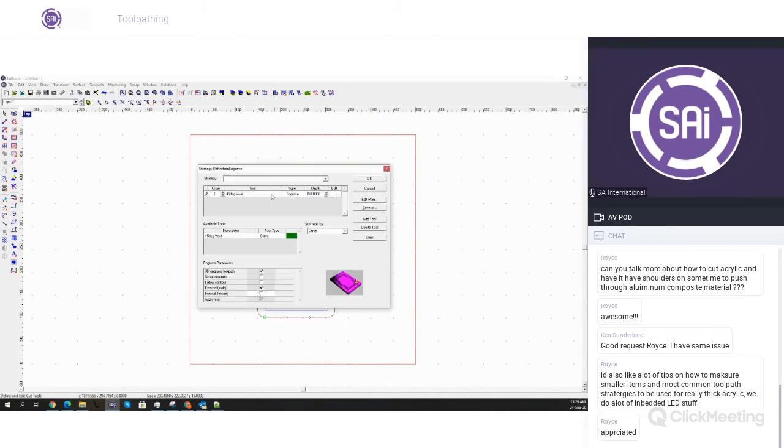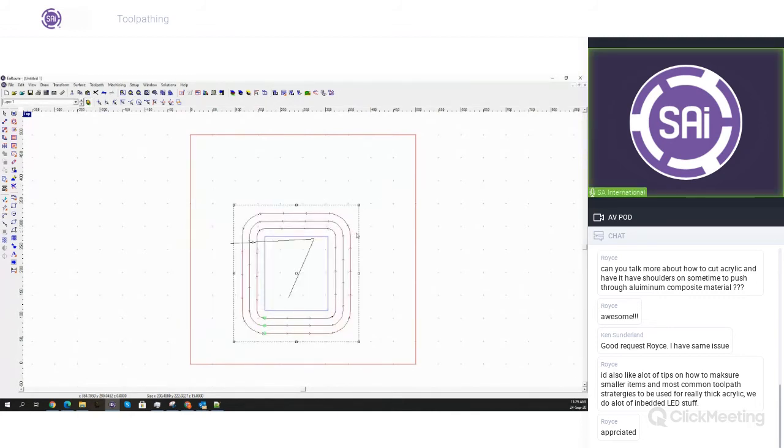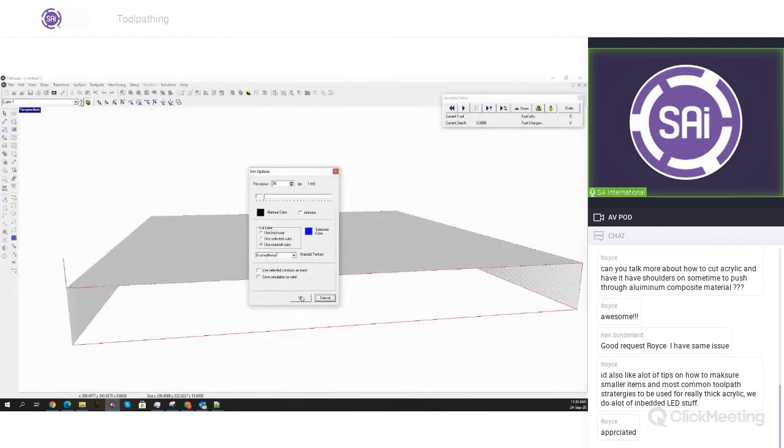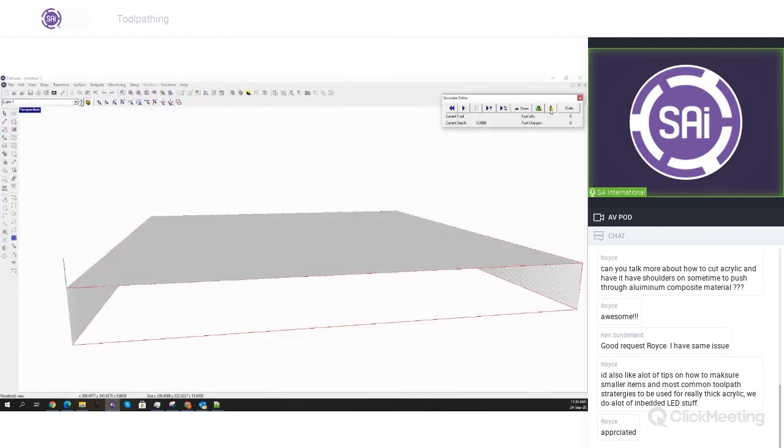And we'll cut this to 50 as an external one. As you can see here, it has put 3 tool paths around it. So it'll use both the shape of your tool, the 45-degree cut, and then the cutting depth of it to add additional contours. And this way it's going to cut down into the material as following.